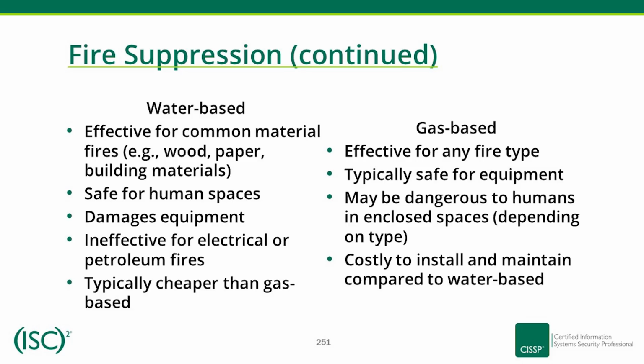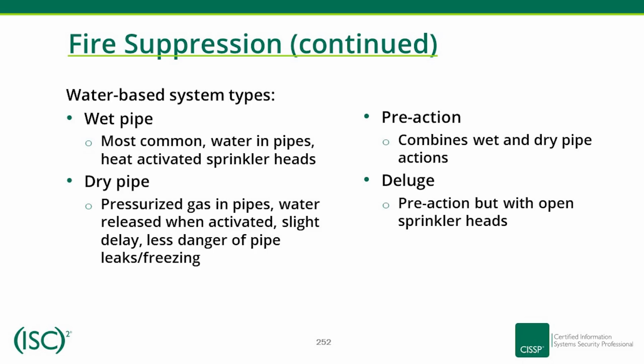Typically cheaper than gas-based. Gas-based: effective for any fire type. Typically safe for equipment. May be dangerous to humans in enclosed spaces, depending on type. Costly to install and maintain compared to water-based.